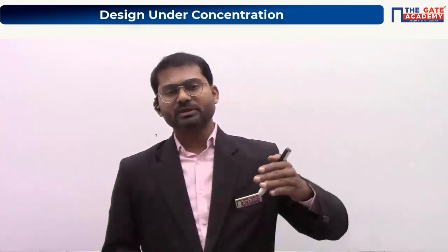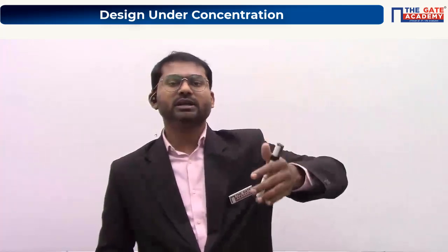Afterwards, if you use the specimen for some application for 5 to 10 years, and constantly it experiences dynamic loads, then after those years, if you do the testing, you'll see that strength is no longer 100 megapascal. It will be less, maybe 60 or 50 megapascal. So the phenomenon of decrease of strength over time due to the application of dynamic loading is called fatigue.